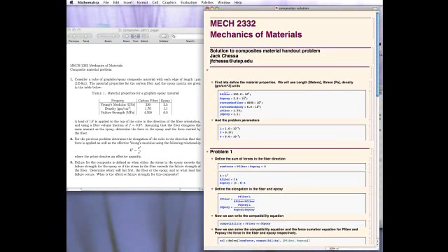All right, so the first thing we do, other than having a nice header here in Mathematica, is we define the problem parameters and the material properties. So we're going to write everything in terms of meters, pascals, and the densities we'll keep in grams per centimeter cubed. There's actually a units function that'll keep track of units for you in Mathematica. I really don't like it. I don't think it works that well for engineering problems, so I'm not going to use it. I'll just keep everything in meters, pascals. So we get the exponents here.